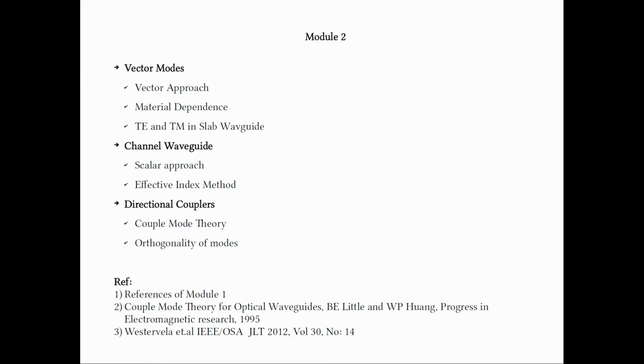We have considered what is called the coupled mode theory to study this process, where the mode field is considered as a superposition of the modes of the individual waveguides, and apply it into the wave equation to obtain the variation of the fields. The coefficients A and B, or U and V, whatever we considered, are considered to be variables with respect to Z, and represent the power exchange process.